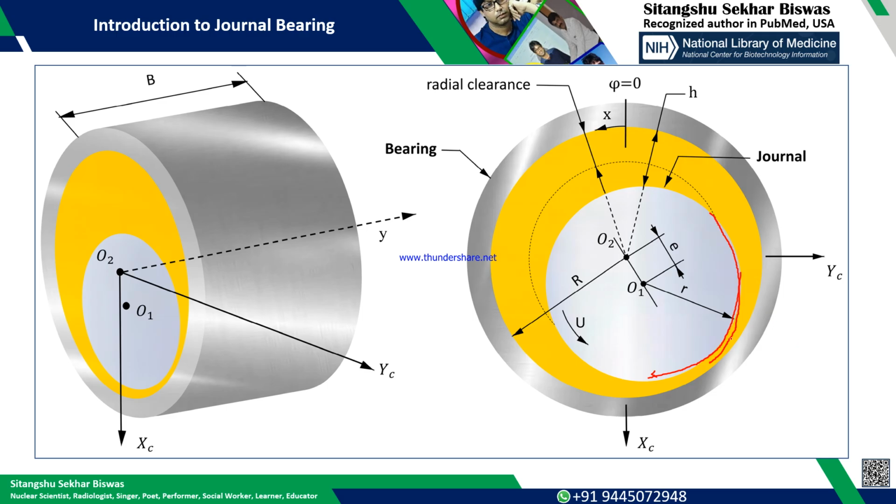Hence this area will experience lower pressure, static head, and from that Newton experiment, we conceptualize the inner lining of the babbitt or the bearing shell will be at rest. So there, comparatively, the static pressure will be high. So this will create one lifting force, which will be basically floating the shaft or the journal inside the shell.